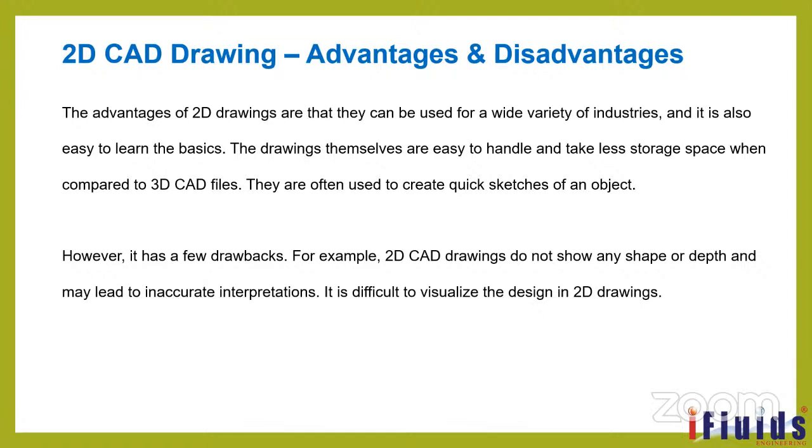The drawings themselves are easy to handle and take less storage space compared to 3D, where there will be solid objects. They are often used to create quick sketches of an object. Whenever we want to make a line diagram, or a rough draft sketch of the plant or a GA drawing of the equipment, the preferable one is a 2D drawing.